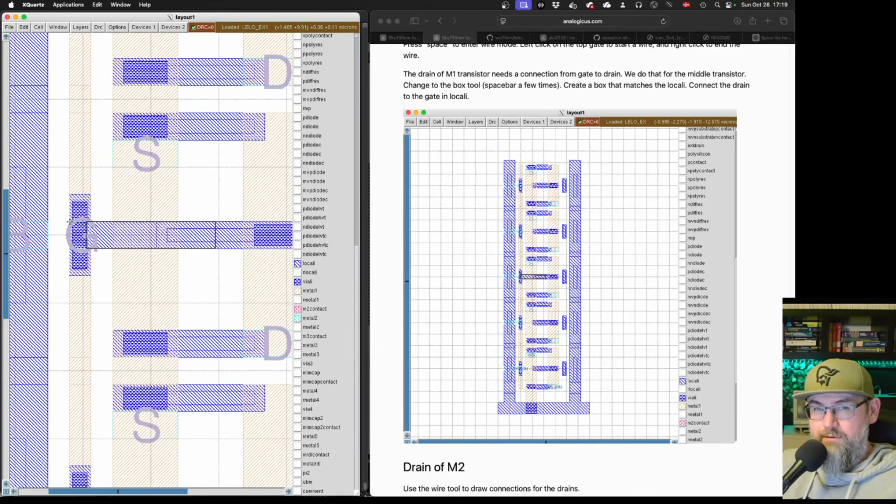Usually those dangling bonds are negatively charged, so they add hydrogen in the silicon oxide in order to sort of tighten those or fill those holes. But those hydrogen bonds are very weak and it's easy to break. Now those can break and you can actually create a dangling state, or a vacant state, where electrons can jump into, and this can actually change your threshold voltage.